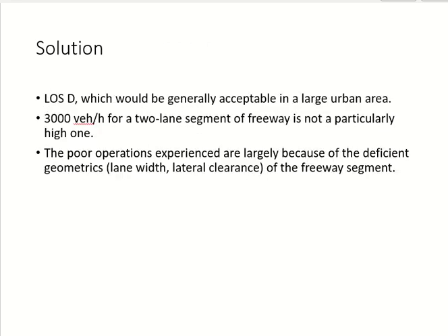Okay. I'll come to it. Now you got level of service D, but in free flow condition. Free flow condition is good or bad? Good, right? Free flow condition is good. D is good or bad? Tell me. Not good, right? Okay, so there's a mismatch, right? We are in free flow conditions, but the level of service is still D. What's the reason? It should not happen.